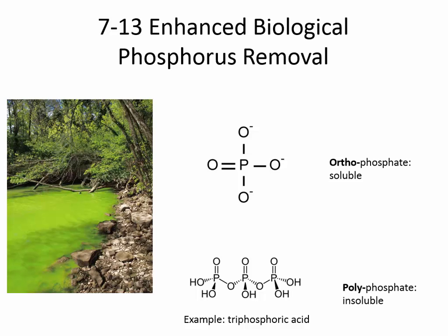And then they added also a little bit of polyphosphate because they knew that that was going to help precipitate calcium onto the pipes. And so it helped prevent corrosion. This is a corrosion control chemical, because if you just put distilled water through a steel pipe, the distilled water will actually dissolve the steel pipe over time. It will cause corrosion and rusting.